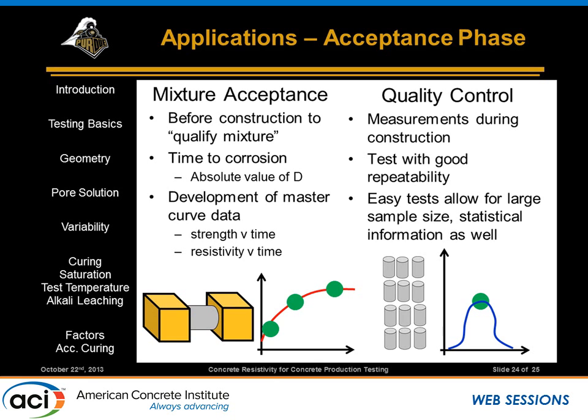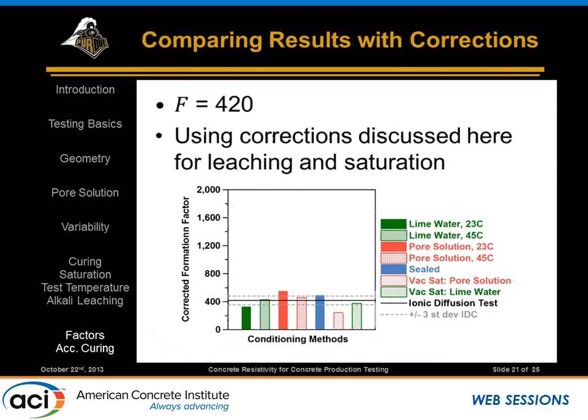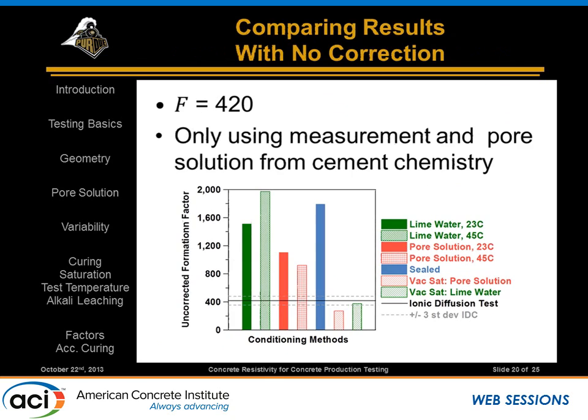Yeah, so just to go back on why we're leaning toward the sealed way right now, essentially, even if you put it into a bucket filled with water, it's not saturated after 90 days. You can take that sample, dry it out, resaturate in a vacuum, and you find out that you're not anywhere near saturation. So we're not at saturation when it's in a bucket, plus we're providing it all the opportunity that we can to leach like crazy.